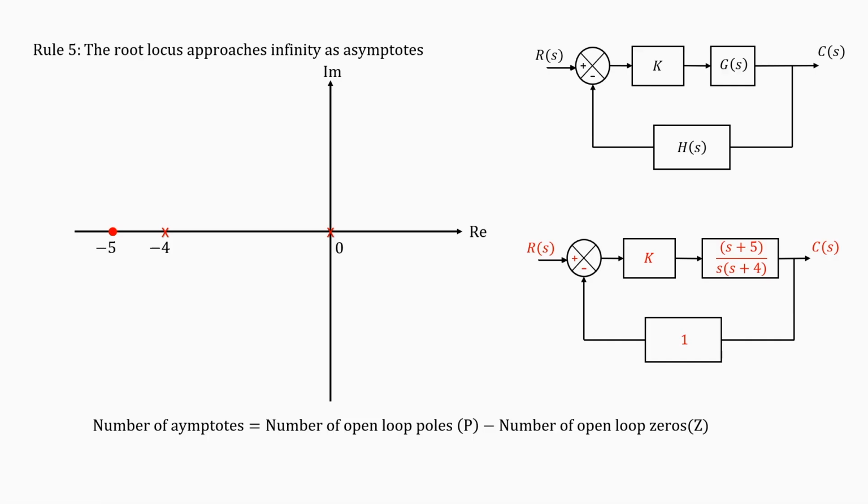Remember, I said that, okay, now see what are the informations that we have. We know that this entire line lies on the root locus and this entire line lies on the root locus, and we know that the starting points are this. So, they will start like this, from this side also they will start like this, right, because it cannot go in this direction, okay. Can it go in this direction? If it goes in this direction, then one branch must come out in this direction also, right, because they have to move symmetrically. They must be symmetric about the real axis, but there is only one pole here. So, only one branch can come out of a pole. Where will the other branch come out? There is only one starting point at that point. So, there is no way that this can come out in this way.